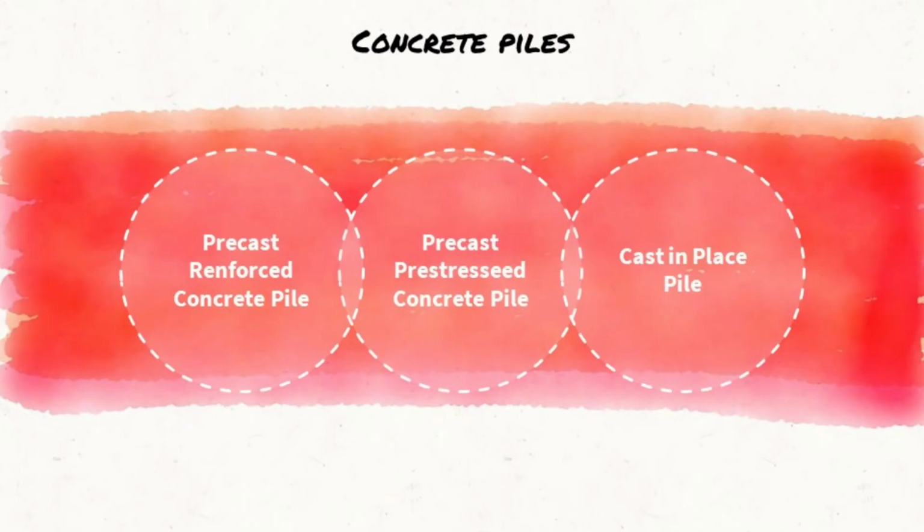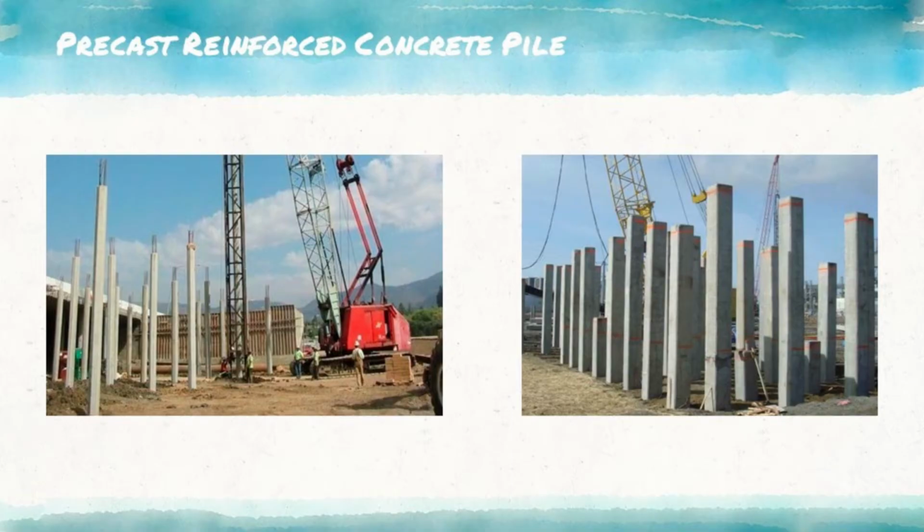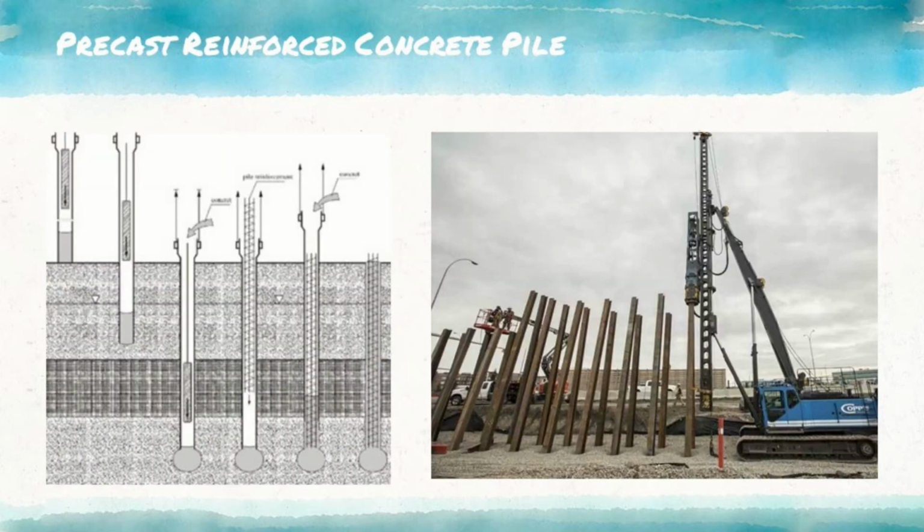B. Concrete piles. 1. Precast reinforced concrete pile. Precast reinforced concrete pile is a pile of reinforced concrete that is molded and cast in the concrete reference. Then once it is strong enough, then it lifts and fixed. Since the tensile stress of concrete is small and is practically considered to be zero, while the own weight of the concrete is large, then this concrete pile must be given reinforcement that is strong enough to withstand the bending moments that will arise at the time of lifting and erection.